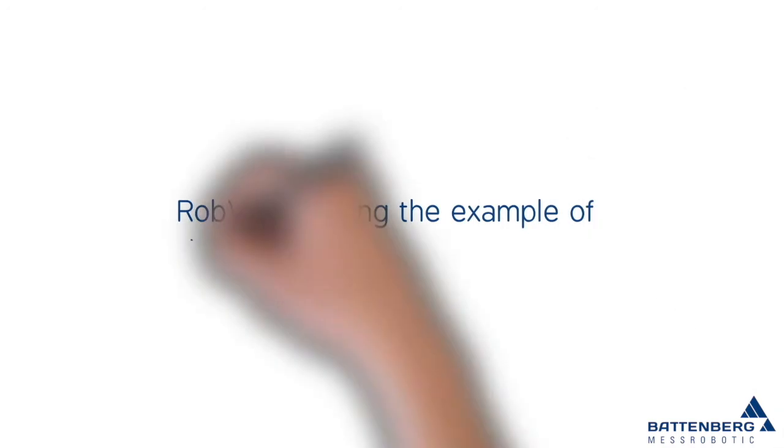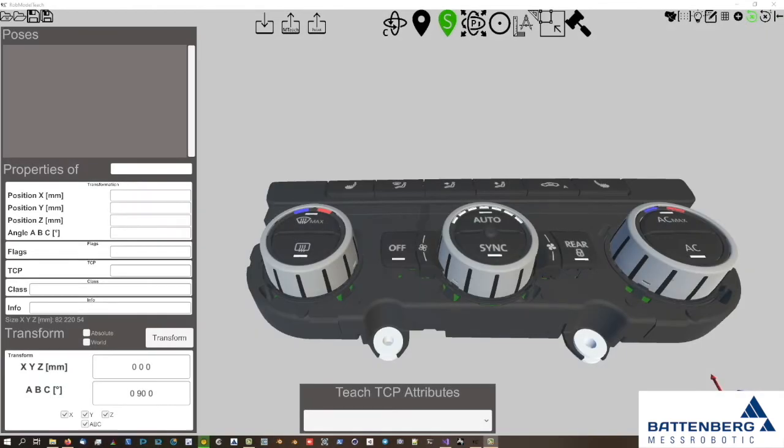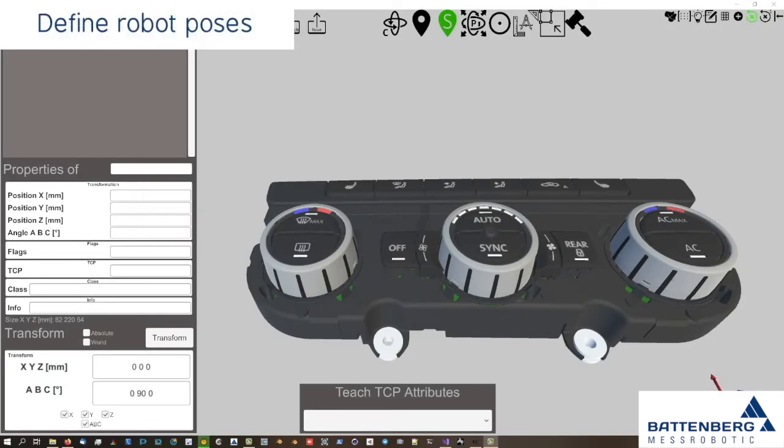Let's take a look at the advantages of the Battenberg RobVirtual package using the example of testing an air conditioning control unit. To define the robot poses, the 3D model of the air conditioning unit is loaded into RobModel Teach. Now you can define as many measuring points as you want, i.e. robot poses, freely on the surface of the model. You parameterize all spatial coordinates either freehand or by entering the values. In snapping mode, robot poses can also be centered automatically.